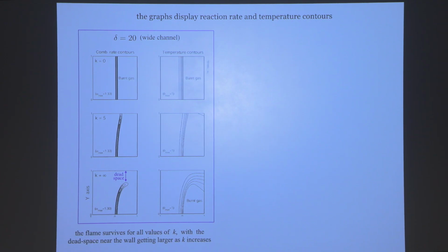In other words, it's a computation that doesn't assume anything about the rate, it's a finite rate, so different values of omega give you a picture of different reaction rates and therefore more or less the shape of the flame or the reaction zone. And these are temperature isotherms. So you see a constant line because of the flat flame.